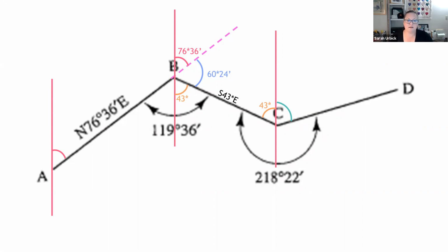Okay, so now we need to find our angle off of our south line. So from our south line backwards, we know what this angle is. That's our 98 degrees, right? So we take our 180, subtract that 98 to get back up to this line from our north-south axis.